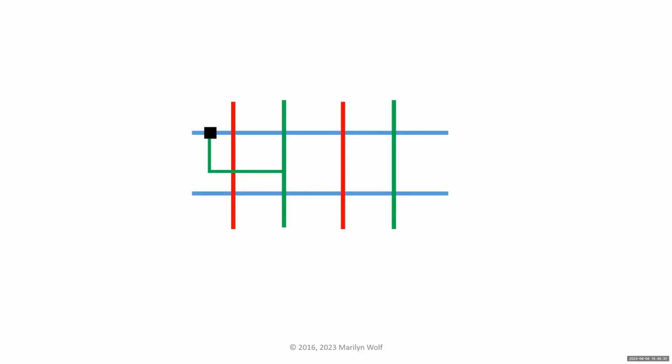And then the crossing between the green line and the red line is one of the transistors, specifically one of the pull-down transistors, okay? You'll see in the piece next to it, there's a red line and a green line going across blue lines, but there is not one of these connections, okay? So on the right-hand side, there is no transistor, there is no pull-down. So basically, we can create this grid of wires, and then we can plop down a little bit of extra stuff where we want these transistors. So we can really think about programming the PLA spatially to create certain functions. Okay.